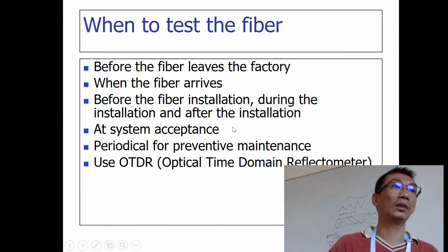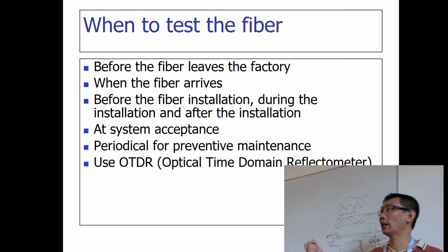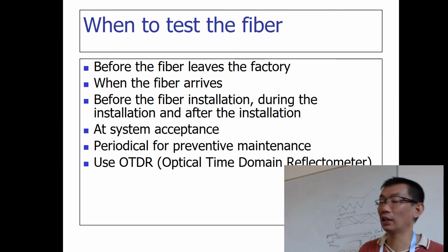So you need to align. After that, you need to test. After you connect the fiber, you send the signal here, receive it here, and see how much loss you have.